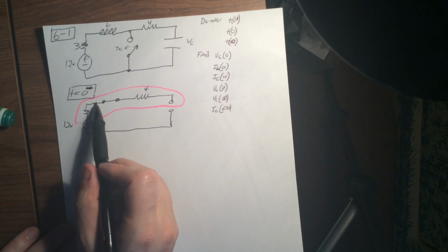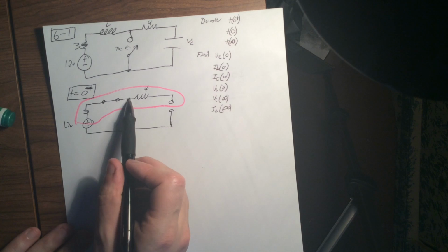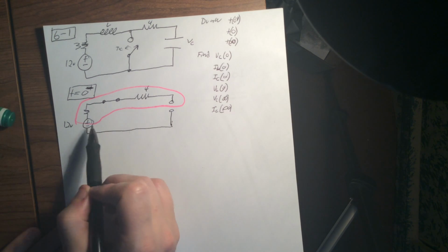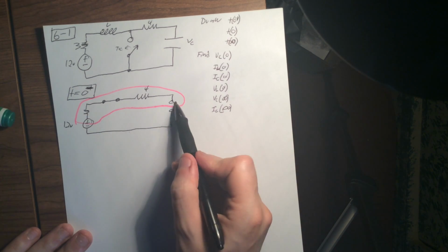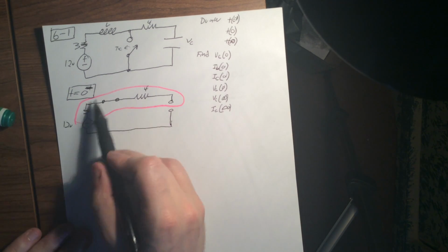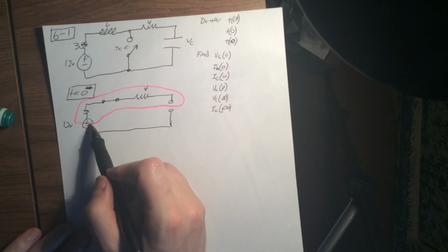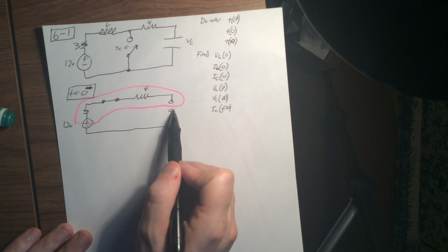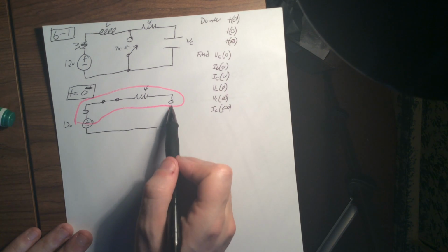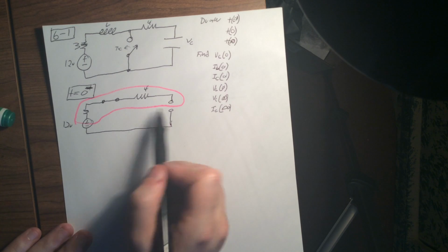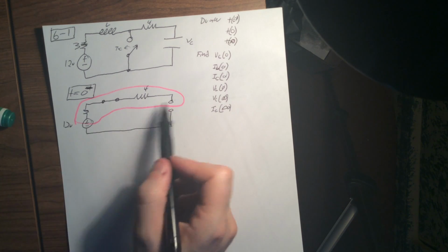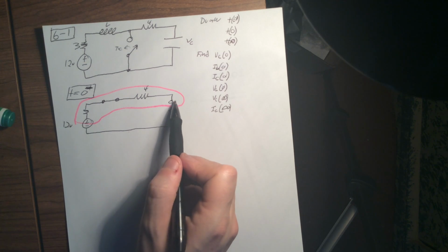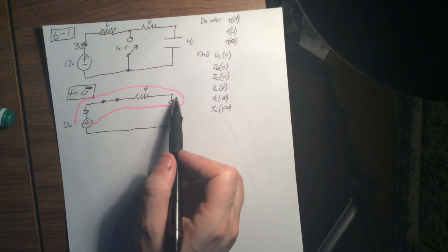So if you put a voltmeter anywhere in this, with one side anywhere up here and the other side down here at ground, the whole thing is going to be 12 because there's no current flowing through. We have that pipe problem that we looked at way earlier, where there's a lot of potential pushing against this, 12 volts of push, but there's nowhere for that push to flow. And if there's no flow, you can't have current. If there's no current going across, the push is constant everywhere. So it's like a pipe with water backed up in it. If I can't get some water out, I can't have flow, and this is all backed up to 12.